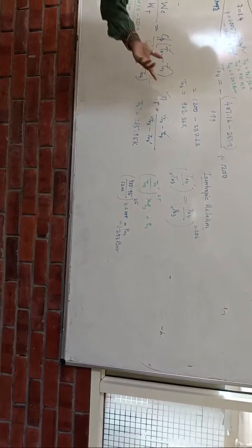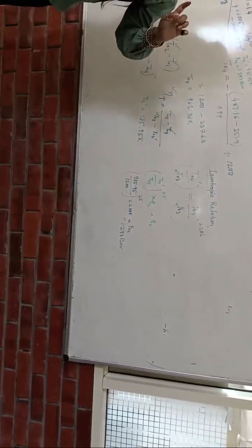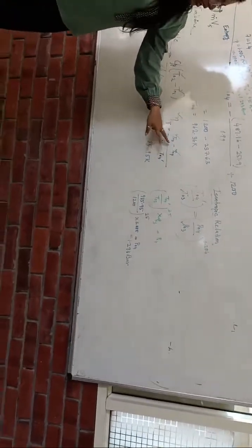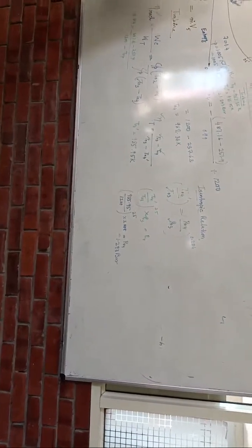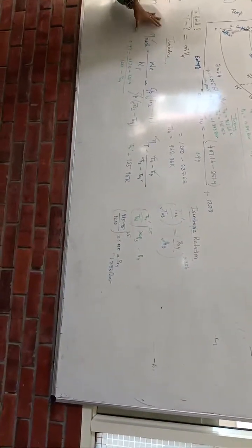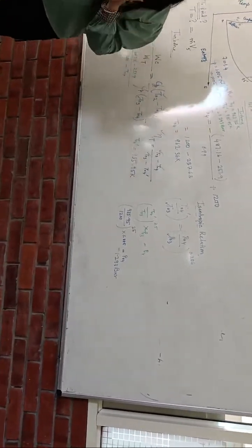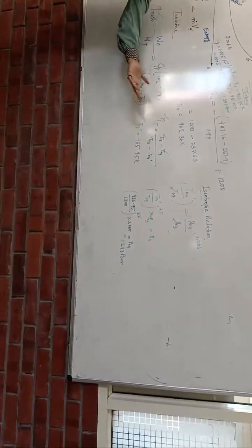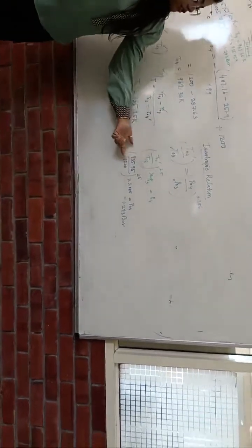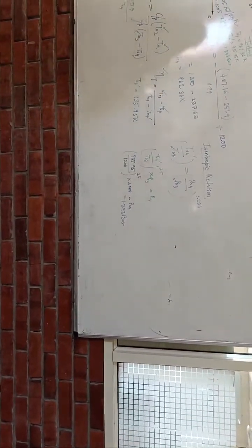The moral of the story is if you take this one first, here you will get two unknowns, so again you have to come back to this. When you are taking turbine, remember if mechanical efficiency is given, you have to take this. If not given, take 100%. And the procedure to find pressure is using the isentropic relation. This is a common procedure for all the components.